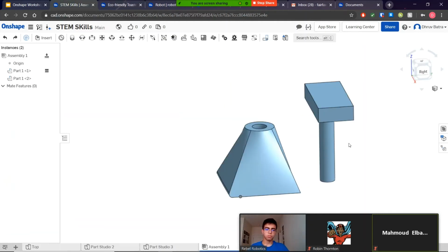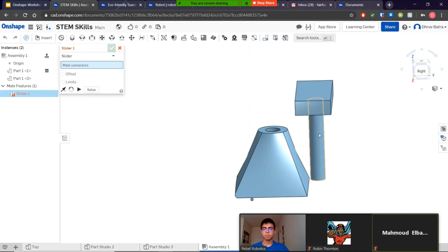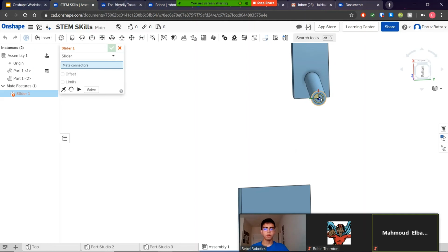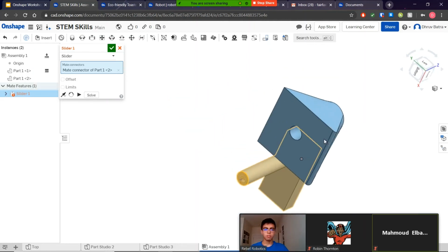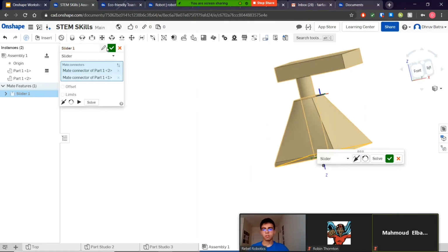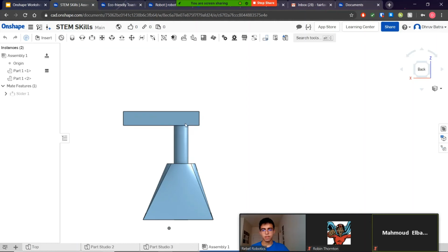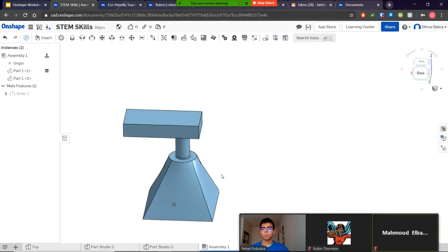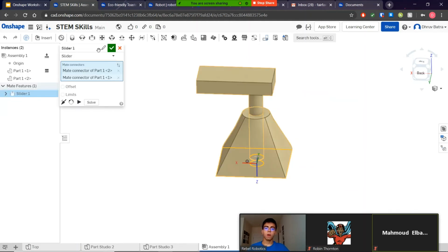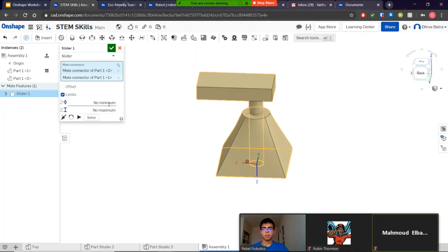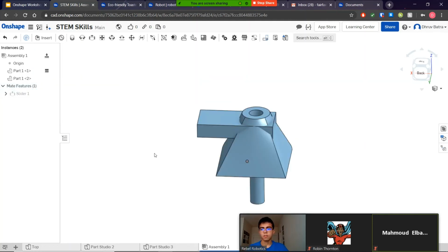You can set these manual restraint limits on the mates at any time just by clicking edit. Okay, so Revolute or slider mate. Slider is the up and down that I just showed you with the toaster lid. Same thing. Let's choose the point on the face, they pop together, and we're good, right? And as I just said, it'll go infinitely in either direction. But if I don't want it to be crashing in here, overlapping, then what I can do is click edit, or I could have just done this when I had it initially up, and I can click limits, and I can set a minimum or a maximum. So let's say... okay, I did it wrong, but you get the point of what I'm trying to say. See, now it'll set the ceiling for it to be at that point.